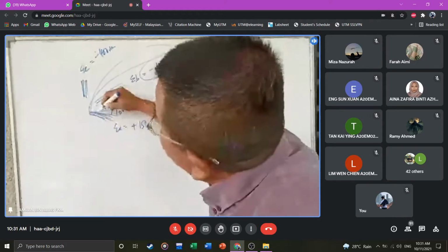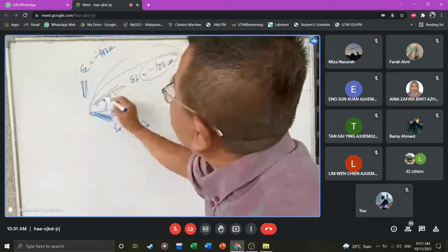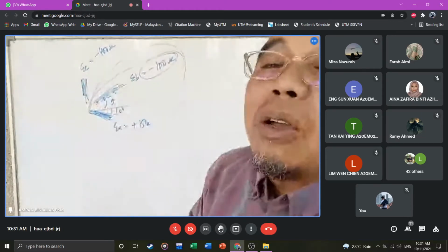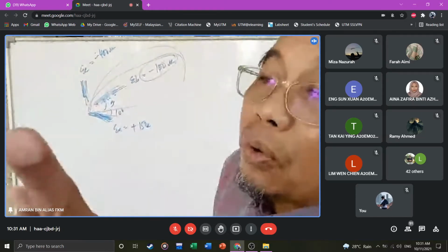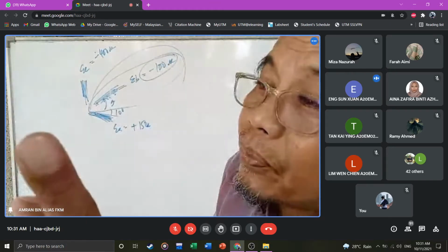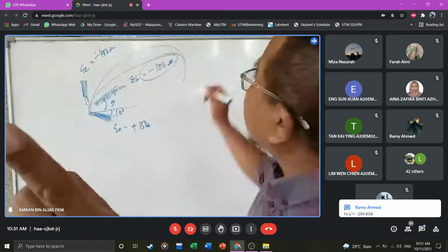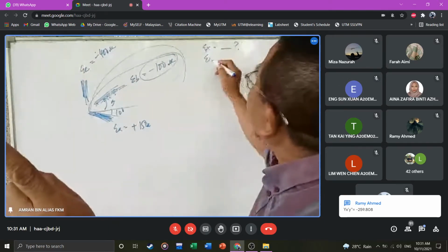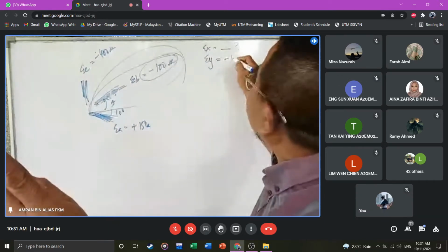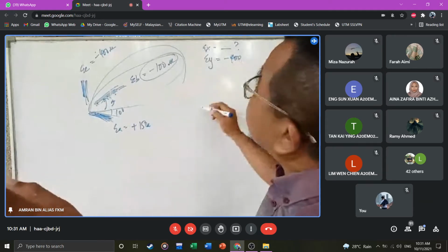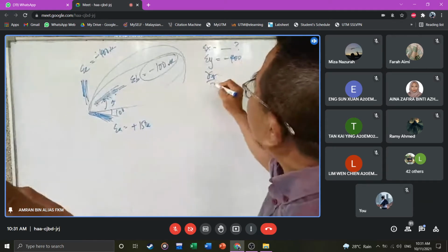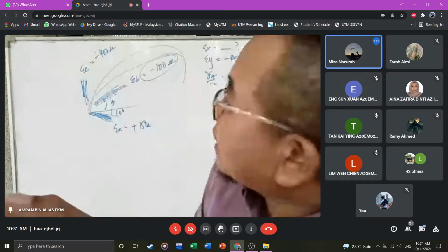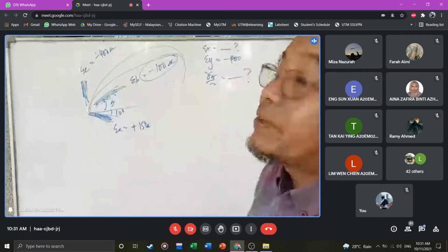I have EA, I have EB, I have EC there. So for this case, which one do I know? EY, yeah, I got EY, minus 400. I don't know EX, I don't know gamma XY over 2. Correct? So how do you solve this one?